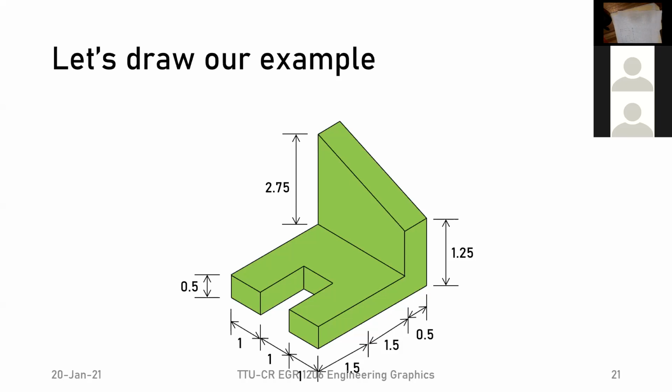And now what we have left is our side view, right? Our right side view, which would come, of course, right down here. That's where we want to put it. So now what we want to do is make our 45-degree angle, and it really doesn't matter exactly where we put this 45-degree angle. Where we put this angle in this parallel direction here tells us how far the right-hand side is going to be moved in there. So maybe we'll put it somewhere here.